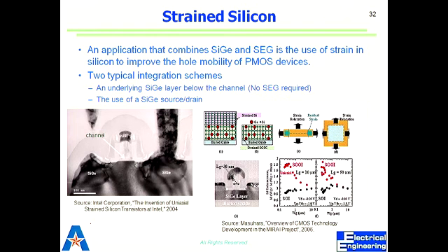This is 0.8 times of what you would get with the normal silicon wafer. Now this is enhanced on top of that. So silicon germanium is 1.8, almost double than what you would get from a bulk transistor. Right? So it's almost double enhancement in current. Drain current is what's important for you, how much current you get in the drain.